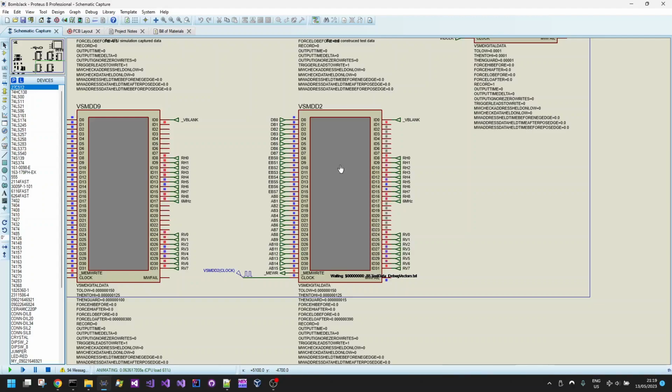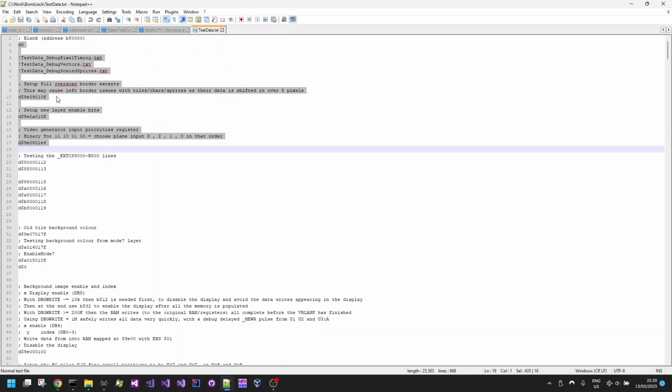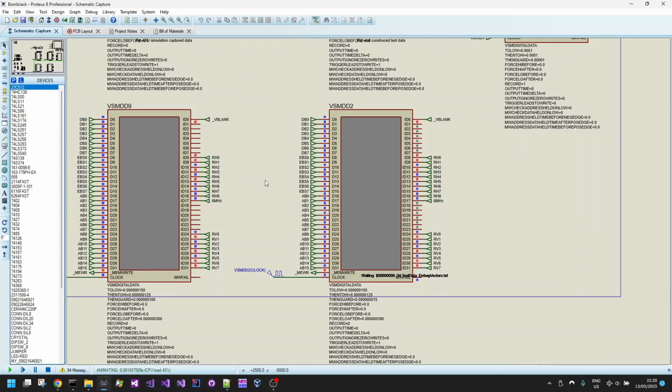And this actually takes an input test data file. So the input test data file looks like this. It describes the input, the 32 bits on the input data lines, and how it should output these 32 bits. So we have the address bus, the 16-bit address bus, plus the 8-bit extended address bus, and then the 8 bits here for the data bus. And all of these values can wait for the internal horizontal and vertical position, and also the feedback.